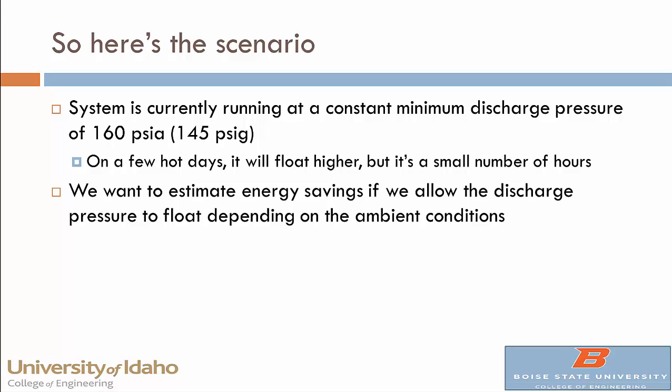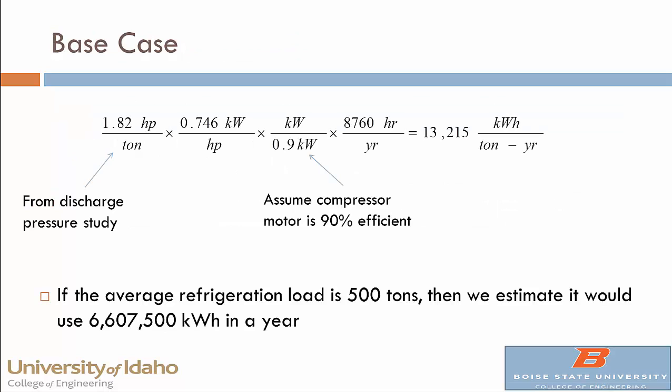So the scenario is this: the system's currently running at 160 psi. We want to see how much energy it'll save if we go to a floating head, which is called a floating head pressure. So here's the base case, right? 160 psi all the time.